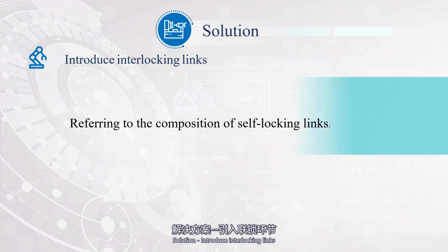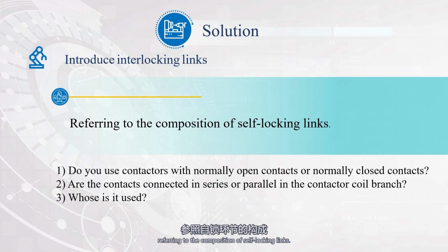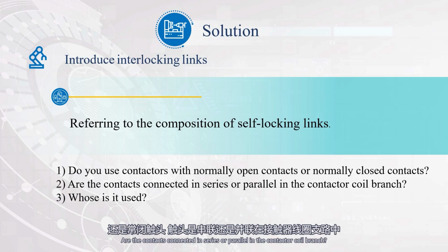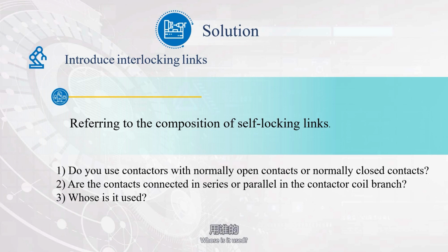The fuse mainly consists of three parts: a fuse seat, a fuse tube for installing the melt, and a melt. The melt is the core of a fuse. It is often made into filaments, sheets, or grids. The materials used to make the melt are usually lead tin alloy, zinc, copper, silver, etc., depending on the requirements of the protected circuit. The melt tube is a protective shell of the melt.